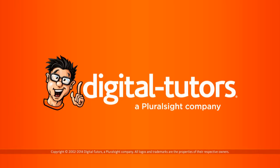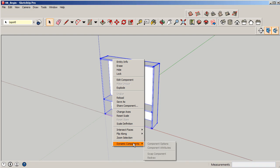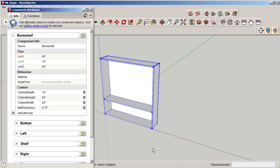In this lesson, we'll begin applying formulas to some subcomponents. Alright, so we should have every component in place. So go ahead and click on it and right-click your element. So we should have our component with our subcomponents. If we go to Attributes, we should make sure that each one of these options here are custom. Our depth, height, and width are all set to the option mode using the Details box.